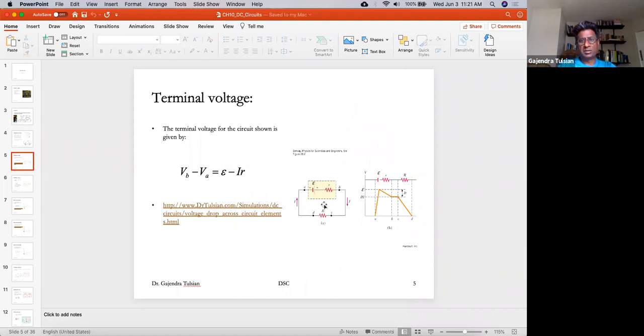But this is what you need to be aware of. And when a battery dies, you can think of it as the internal resistance going to infinity, being large, and then you don't see any voltage outside, and you can draw very little current from it. So that's a battery dying.